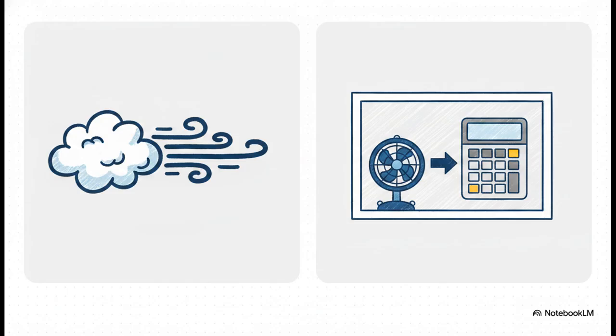So, a quick recap. Last time, we established that wind does most of the heavy lifting outdoors. As long as you've got natural ventilation, specifically wind speeds of 0.5 meters per second or greater, it sweeps the hazard away and dilutes it incredibly fast. But in closed spaces, well, they're a completely different beast. You obviously can't rely on a fresh breeze inside a sealed pump room, right? You need mechanical help. And here's the absolute golden rule for that. Simply saying, hey, the fan is running, is never, ever a valid engineering justification. You need real, calculated numbers.